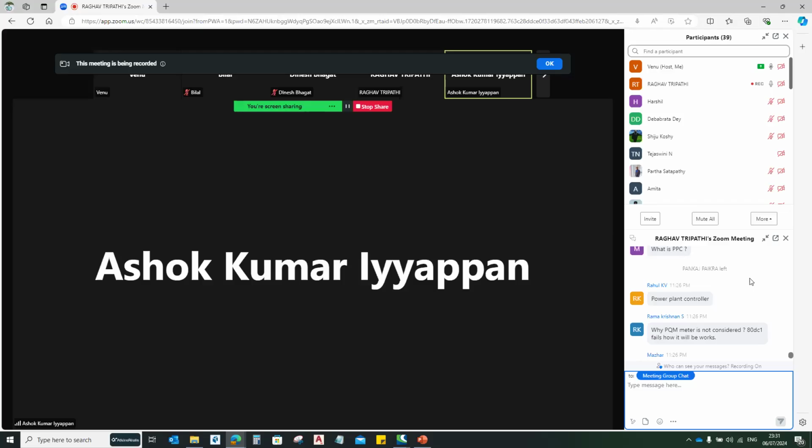For example, if you consider a 400 kV substation connected to one generation station, the 400 kV is part of the national grid, and the generating station is part of the DNO or some user. In that condition, the generator protections will be on the generator and DNO end, and feeder protections as well as other substation control equipment will be in the national grid entity.